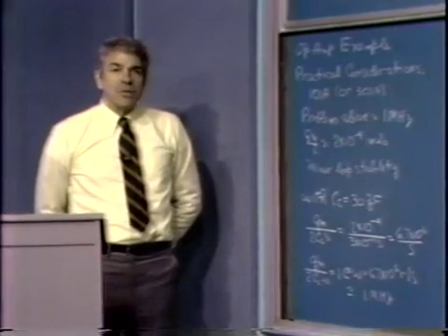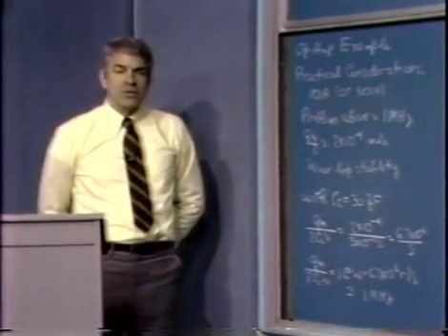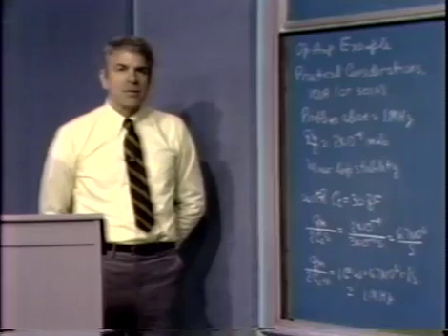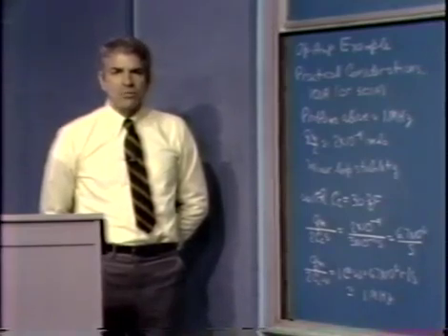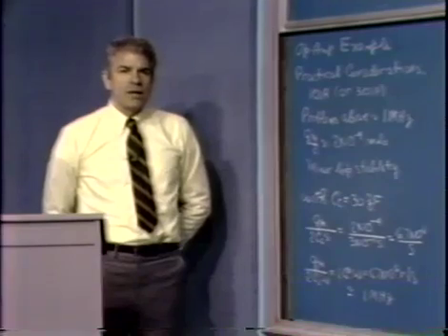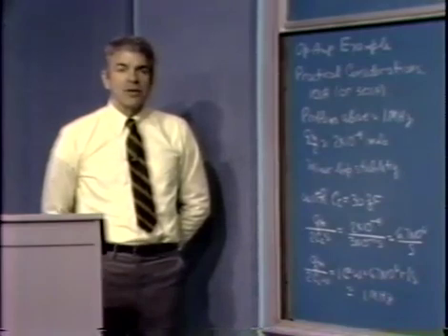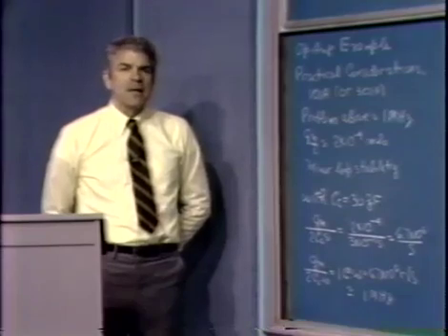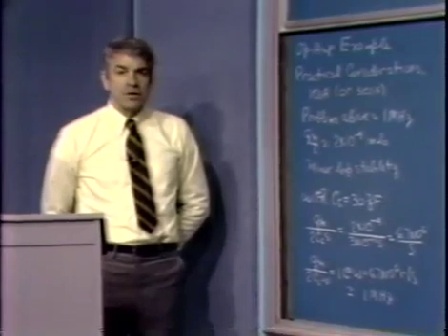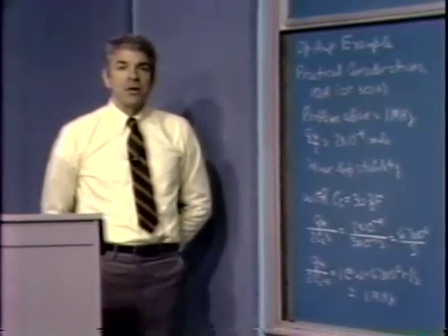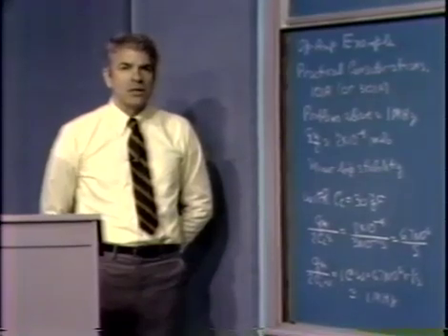One kind of compensation that we can implement very easily in minor loop form is so-called single pole compensation. What we do there is use a single capacitor as the compensating element. That's sort of a degenerate case of a two-port, and if we go through the numbers, we find that the transfer admittance for a single capacitor is simply equal to the value of the capacitance, let's call it C sub C, times S. Consequently, when we evaluate our approximation to the open loop transfer function of the amplifier, it would be G sub m over 2 times C sub C S.